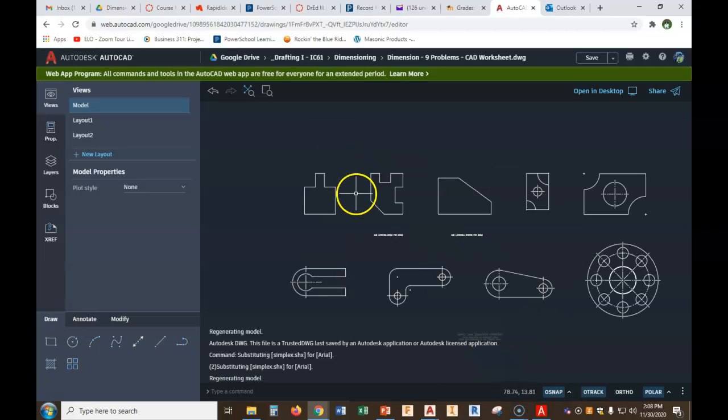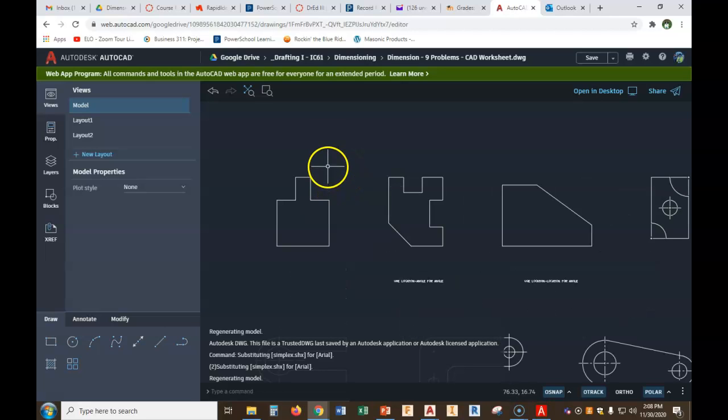So remember, what we're doing is we are dimensioning. I like to personally dimension the actual cuts that are made or holes that are drilled or whatever the case may be, because that helps the person that's creating it. And don't forget now, like the top of this thing has 3 parts, 1, 2, 3. We're only going to dimension 2 of the 3, and then we're going to give an overall width. How about up and down? 1, 2. We're only going to give 1 dimension and then the overall height. The other one we don't need because of that, okay? So this one, look at this, 1, 2, 3 parts. We're only going to dimension 2.